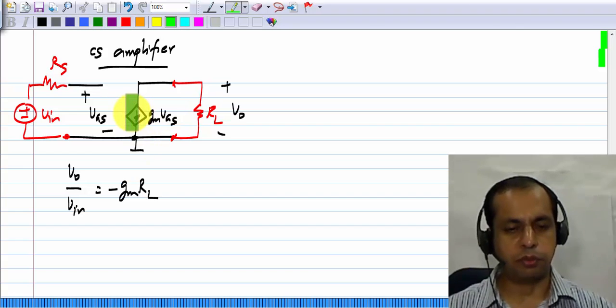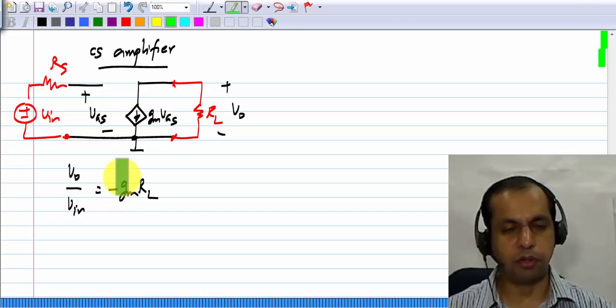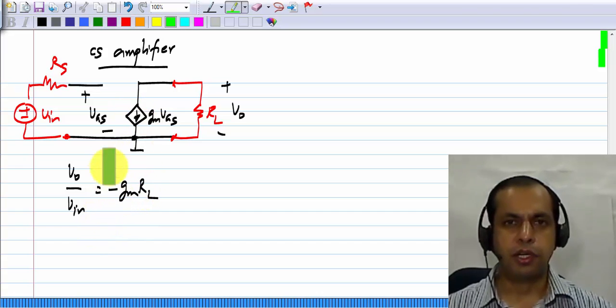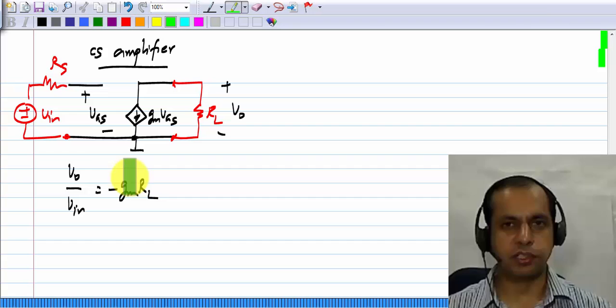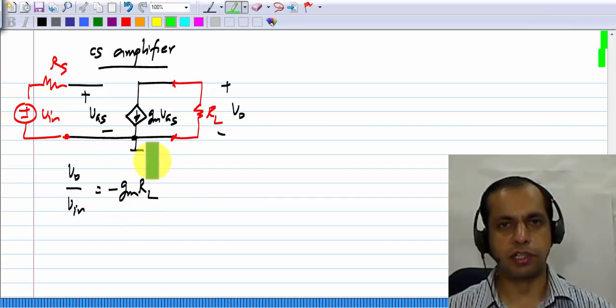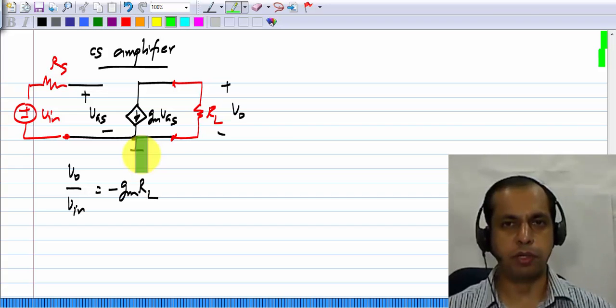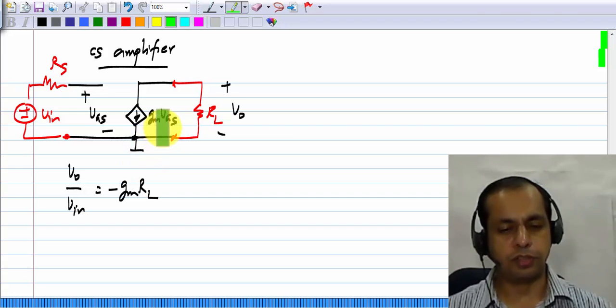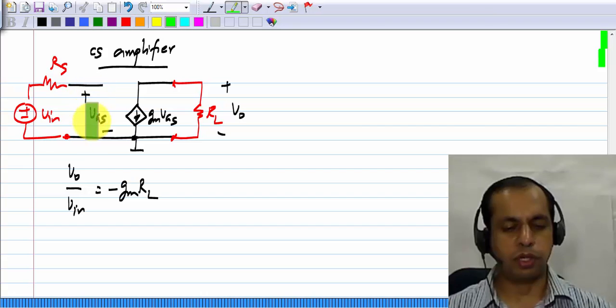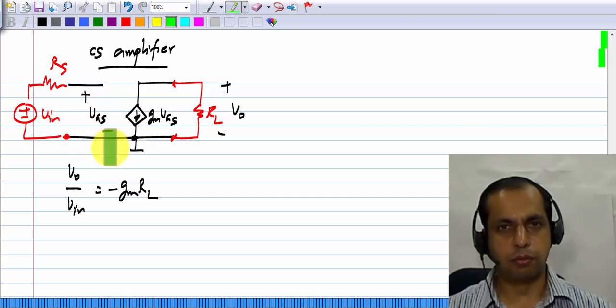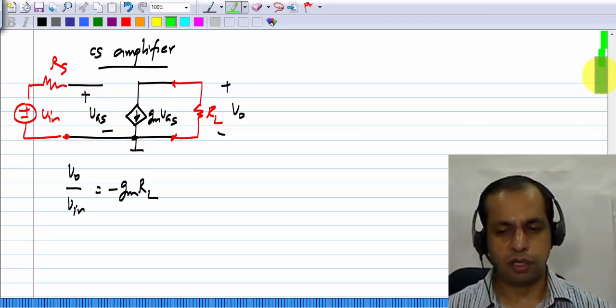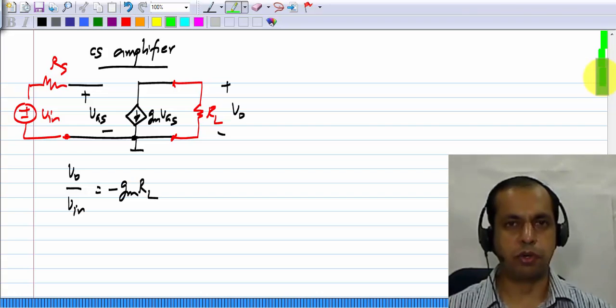Or you may want a voltage controlled current source just like the MOS transistor, but it shouldn't depend on GM. Like I've said before, these characteristics of semiconductor devices like GM, the transconductance and other parameters, depend strongly on temperature, and they also vary quite a lot from device to device. So it is useful to have something where you could still have a voltage controlled current source like the MOS transistor, but its characteristics do not depend on the transconductance, which makes it more accurate.